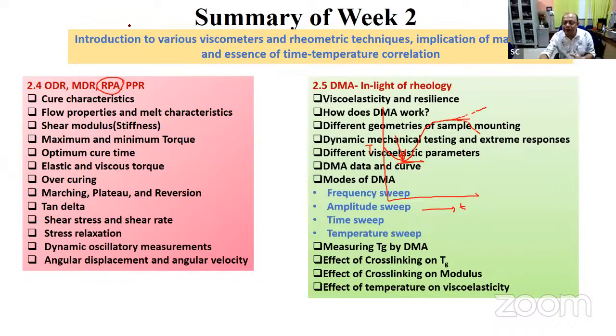So I'm sorry I have written that in this dashboard already, but again, I try to cover in parallel not only the parallel plate rheometer but also DMA in light of rheology. In light of rheology means, again, you have to assess the terminal part of the master curve. Remember what master curve means? Like modulus as a function of, say, G prime or E prime as a function of time or temperature. It's equivalent, let's say time or temperature. Okay. So you get a glassy state, glass transition, and then finally rubbery plateau and flow. And this flow, the material becomes more like a liquid state.